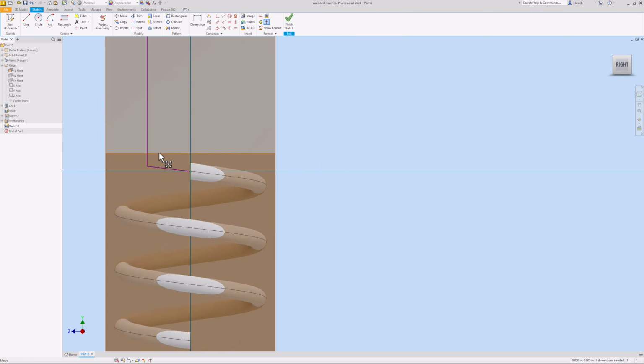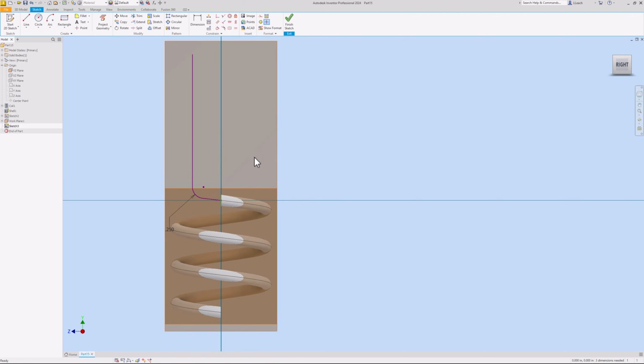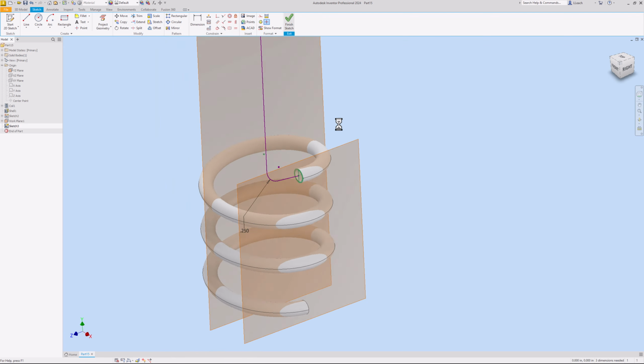We don't want our straw to have this sharp of an angle. So I'm going to use the fillet. And what do I want that to be? I want that to be 0.25. Just make it the same. I'm going to make the radius of this fillet the same as the diameter of our straw. I don't know. Like so. And then I'm going to finish my sketch.